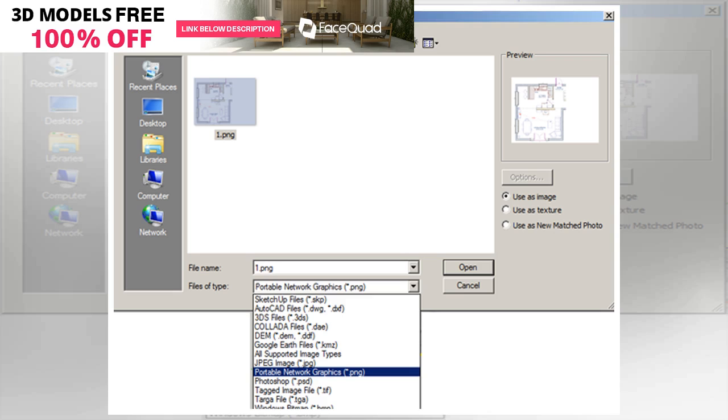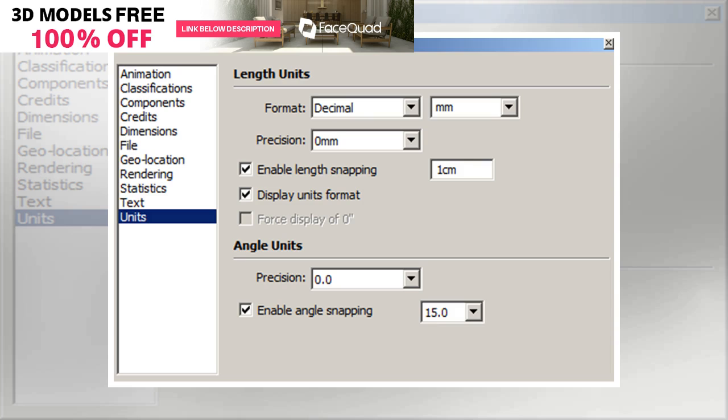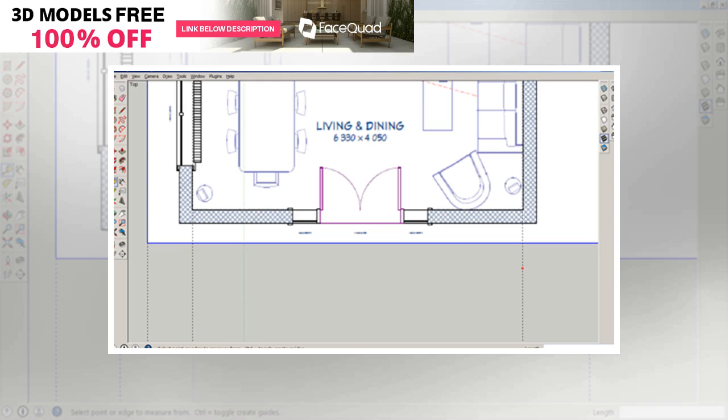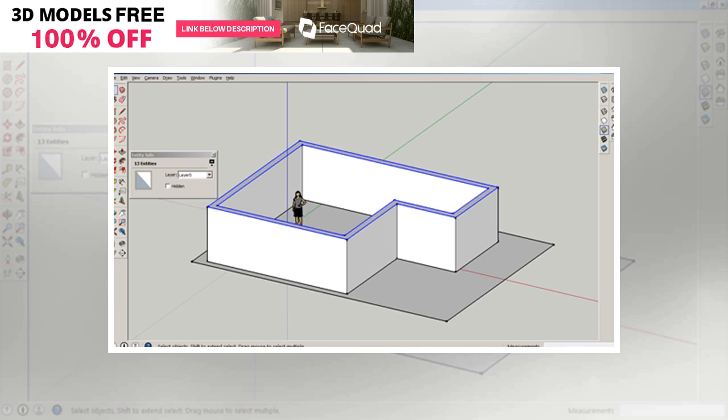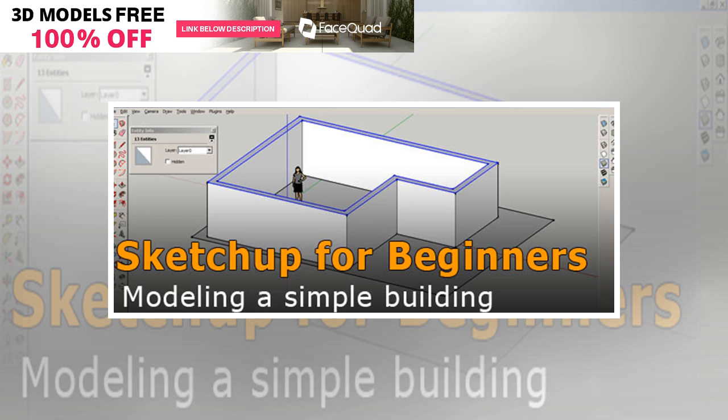To specify the true value, just type the correct dimension, 6330 mm, right after you measured it. Note, do not try to place the cursor in the text box, this won't work. Just type. Again, if you are using units that differ from default units, for example, model units are millimeters and you want to enter 14 inches, you need to type units as well right after the numerical value. Possible dimensions to be typed are 1'2", 2500 mm, 2.5 meters etc. Do not type any spaces or dashes. You can omit units, in this case SketchUp presumes default model units.